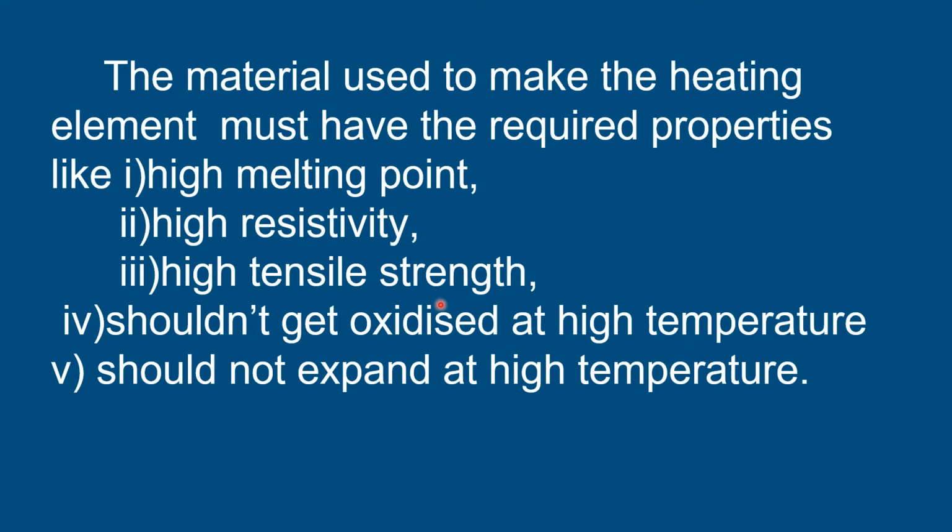The next property is that it shouldn't get oxidized at high temperature. Since this heating coil is getting heated up to a high temperature, it should not combine with, or react with, oxygen in the air. So it shouldn't get oxidized. The next property, it should not expand at high temperature, or else the length of the coil increases.